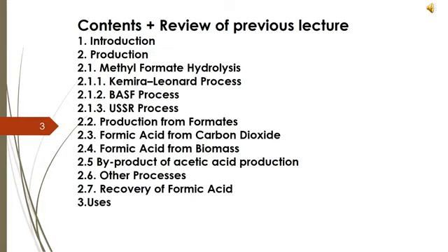And after that, what happened? The distillation is now done in controllable processes in two columns, H and I. In H, first water is distilled, and the concentrated product at the bottom is formic acid, but it is further concentrated in the next column. H is the first product column and I is the second product column.